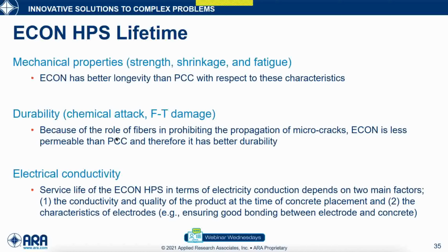One of the big issues, I believe, for bridges is corrosion of the reinforcement. Since bridges are heavily reinforced, when the de-icing chemical touches the reinforcement, corrosion will start, and you will have delaminations, and the surface life of bridges will significantly reduce. So this is the good thing about the ECON system: it can be implemented for bridge applications as well.